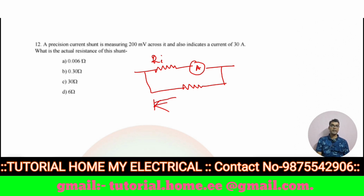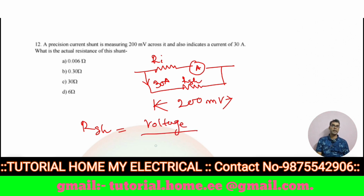The voltage across the shunt is 200 millivolt. Now also indicate current of 30 ampere, means here 30 ampere is flowing. This is RSH. So the RSH is voltage divided by current. What is the voltage? 200 millivolt. What is the current? 30 ampere.